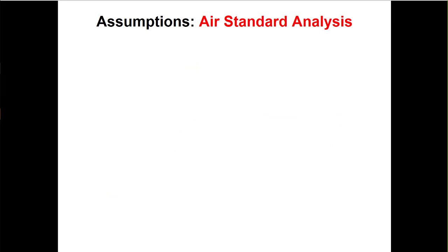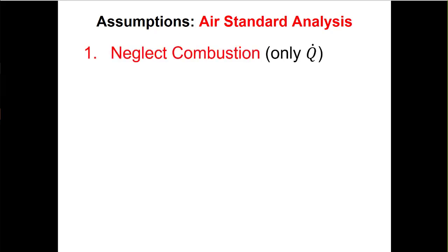So because the working fluid is air, which is an ideal gas, we're going to make a lot of the same assumptions that we did when we talked about internal combustion engines. We're going to neglect combustion. We're going to talk about this always as if heat is coming into a heat exchanger, as opposed to us injecting fuel and then burning it and worrying about that sort of chemical reaction and the changing in the gas.